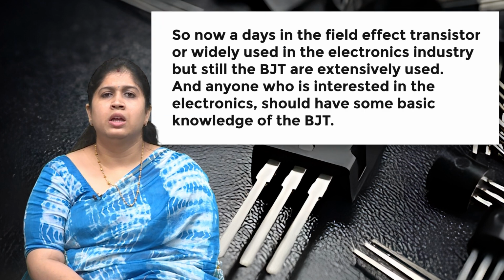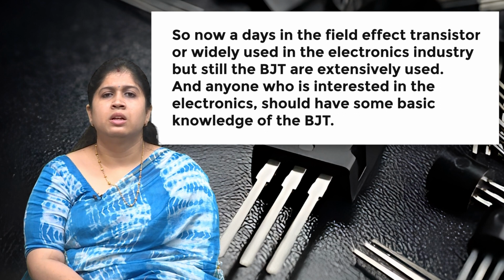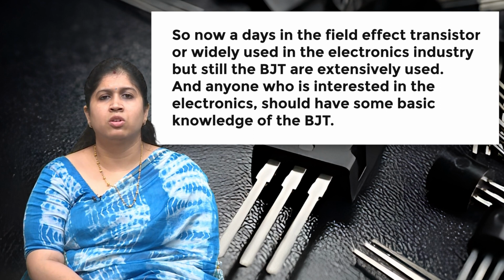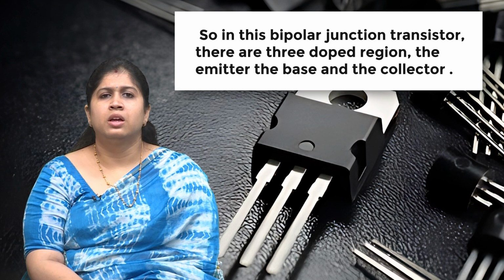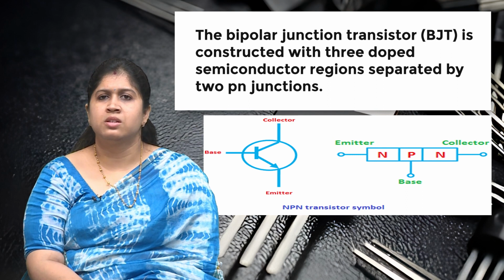Nowadays, field effect transistors are widely used in the electronics industry, but the bipolar junction transistor, BJT, is still extensively used, and anyone who is interested in electronics should have some basic knowledge of the bipolar junction transistor. In the bipolar junction transistor there are three doped regions: the emitter, the base and the collector. The bipolar junction transistor is constructed with three doped semiconductor regions separated by two p-n junctions.